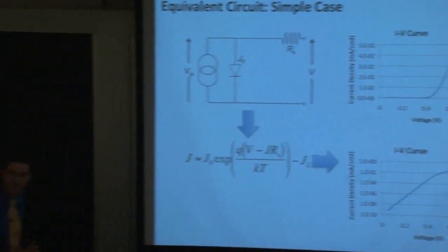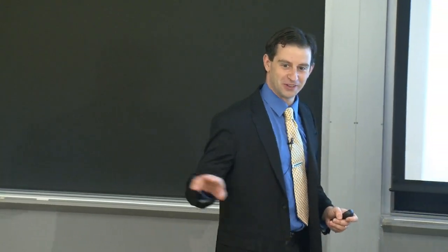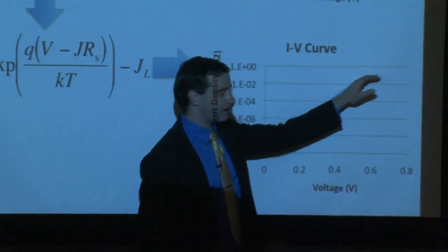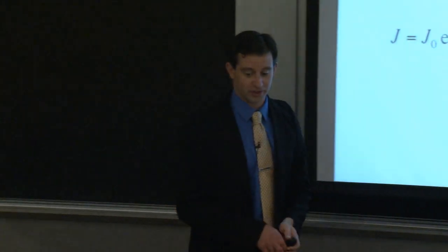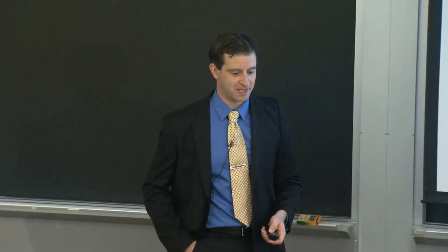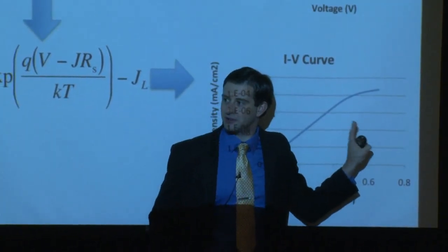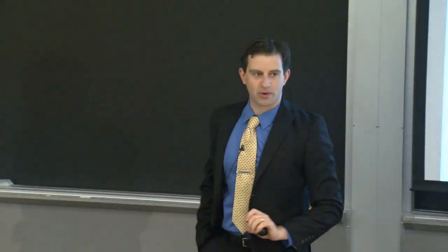So think of it as doing that IV sweep that we did in class the other day, right? You're taking the IV sweep of your device, and you're seeing the impact of the series resistance in the output voltage that you're measuring of your solar cell device, just like we did in class. So again, series resistance will affect you at some point. It is almost inevitable. But you have to design your solar cell such that it affects you only after the maximum power point.